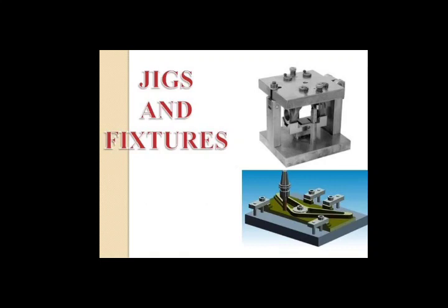This system is not preferable, as it would accept the workpiece only if the workpiece and location system are manufactured without any error. The reference surfaces in this case are parallel to each other. One is needed for reference and the other should be eliminated. So according to the requirement, either the flange surface or the hub surface will be used as the reference surface for location. This is what the design engineer should consider.